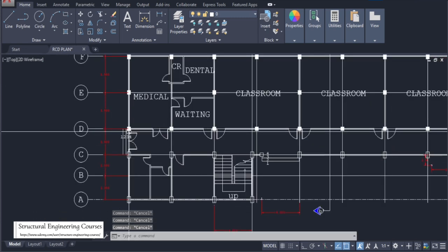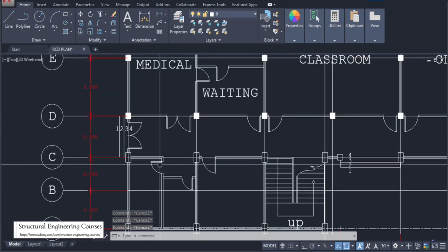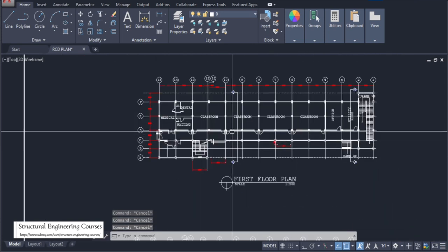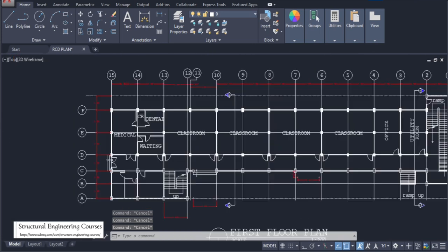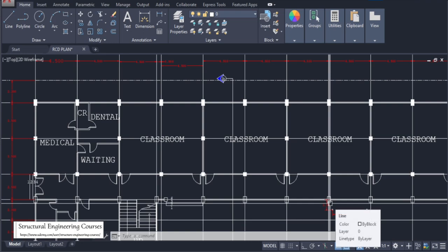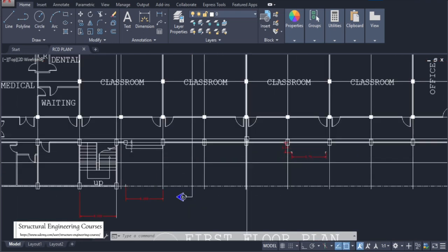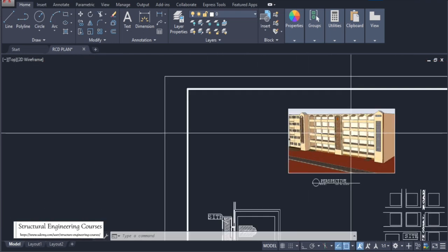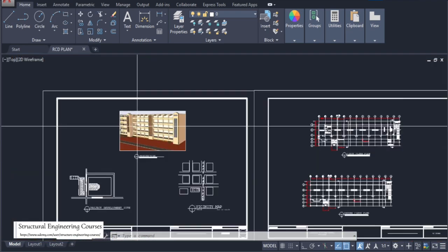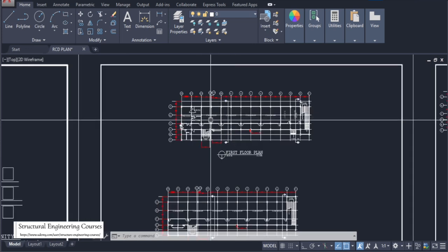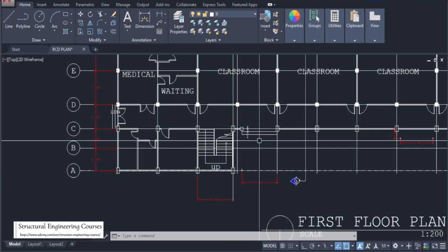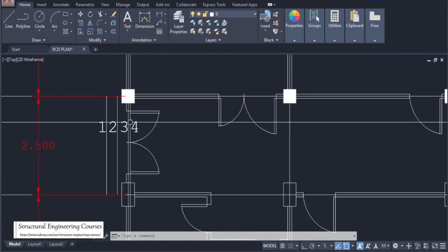And so we have planned one side of the corridor here, and then again here also we can plan the corridor. For the structural symmetry of the building, whatever columns we are providing here, we will provide the mirror image column here. Plus this is the front end of the building, so for architectural aesthetic purposes also, this column will look good here. It is not that columns are always ugly, but they do add to the architectural element sometimes, or they can make the building look beautiful also.